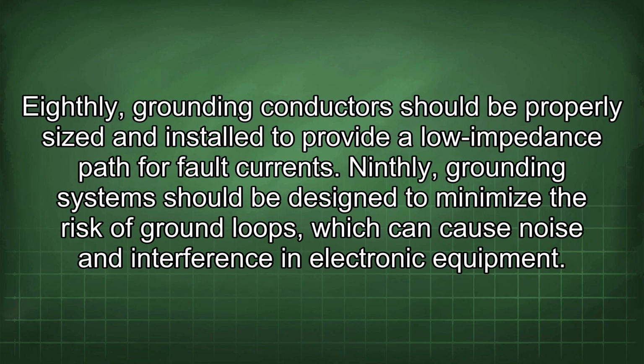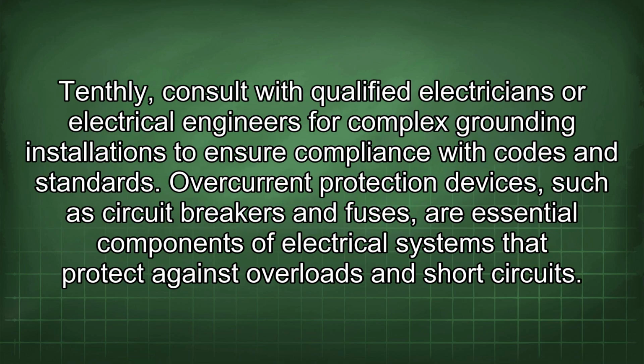Eighthly, grounding conductors should be properly sized and installed to provide a low impedance path for fault currents. Ninthly, grounding systems should be designed to minimize the risk of ground loops, which can cause noise and interference in electronic equipment. Tenthly, consult with qualified electricians or electrical engineers for complex grounding installations to ensure compliance with codes and standards.